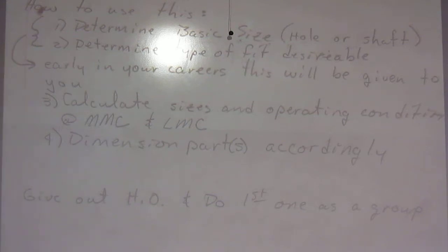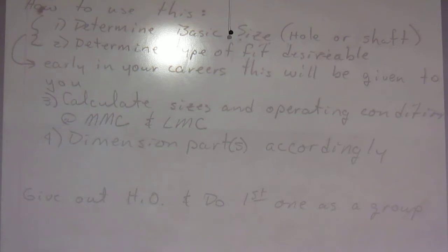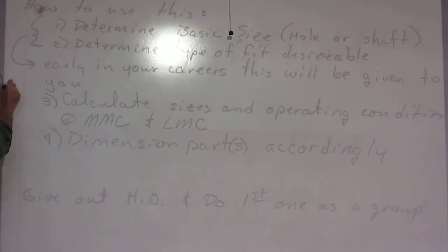You can then dig up the rest of the information, and you can draw and dimension accordingly. So when you get this sketch, your end view might look like something like this. Okay, where I would come in, since it's a shaft, it's going to be smaller. So let's say I now have a nice drafted drawing where I see that view, this view. I'm going to go ahead and put my dimensional information on here. This might be 0.691, and then I might have plus 0.006. I'm kind of doing this bad.